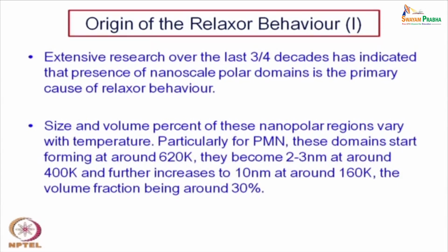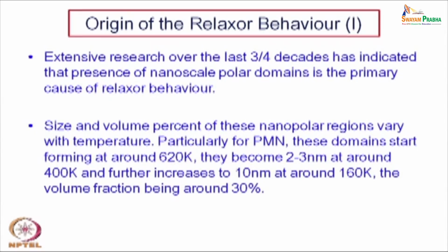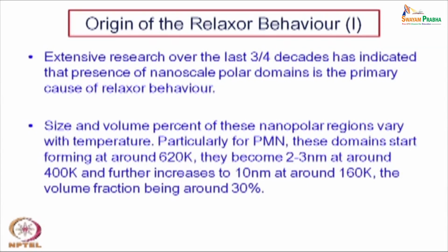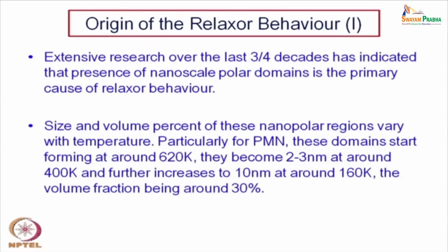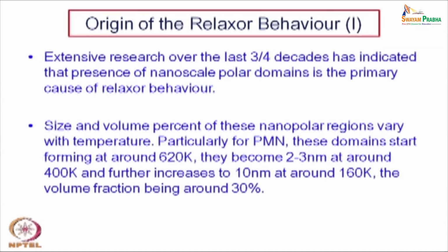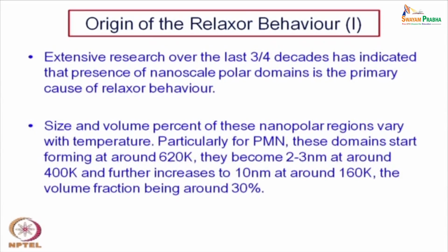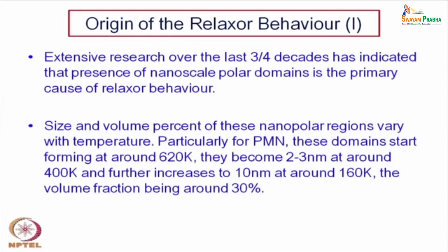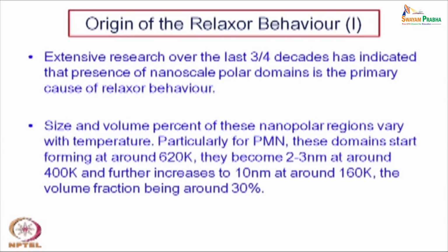Here it is nanoscale domains, very fine nanoscale domains, and they are not a fully ordered structure or a fully crystallized structure. They may be crystallized, but so far as the domains are concerned, they have a disordered structure. Now, because of this disorderedness, instead of a single relaxation time, as in the case of barium titanate, you have a multiple or a spread of relaxation times, or a distribution of relaxation times.